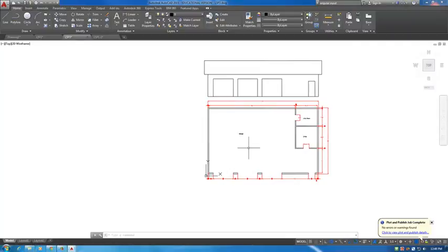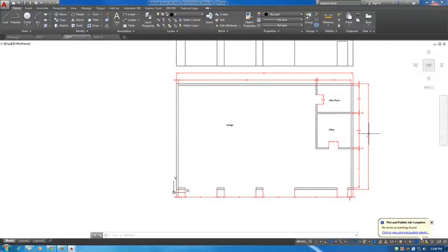If we look at this building, it's 30 feet wide. If we cut that in half, the peak should go right up the middle, so 15 feet is your run to the peak. You take that 15 feet and multiply it by 4, and that gives you your rise.